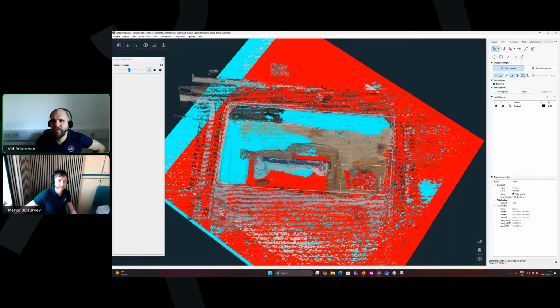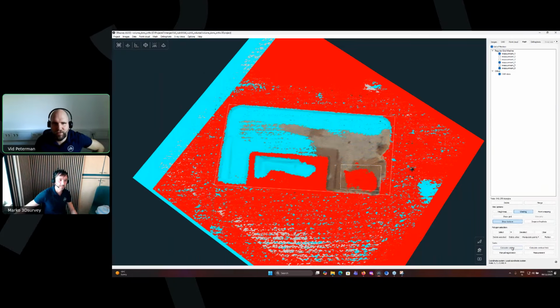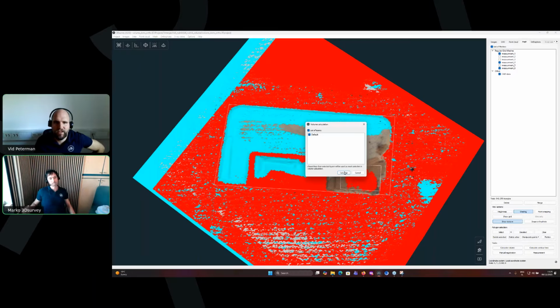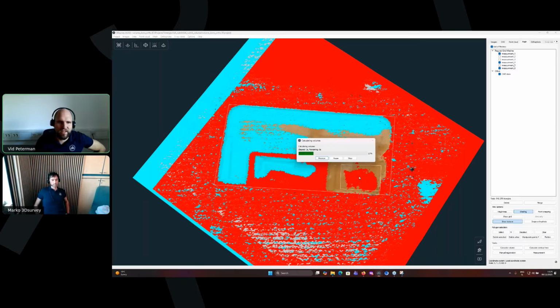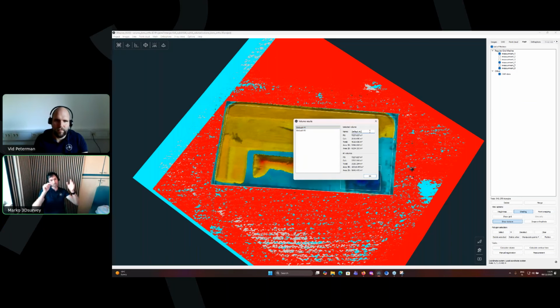Okay, these lines are now on the default layer. We go to mesh, calculate volume. Initial surface will be measurement 1. Final surface, we will leave it on measurement 4 from CAD. We use the default layer, press calculate. It will automatically now select each closed polyline, and it will create 2 separate volumes. So create 10 layers, every layer is a different area, calculate volume based on CAD data, read these layers, and that's it. And you can calculate finally, we always just name them here. Polyline 2. But you would probably have stockpile 1, stockpile 2, sand, asphalt, and so on.